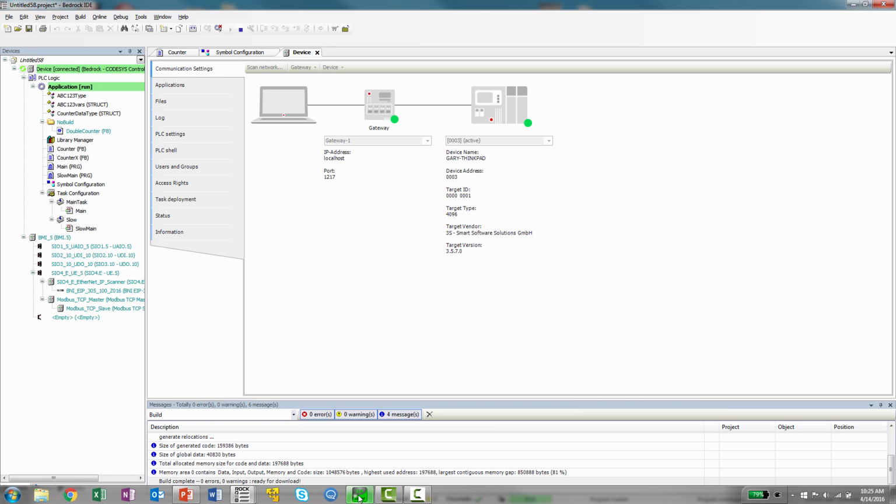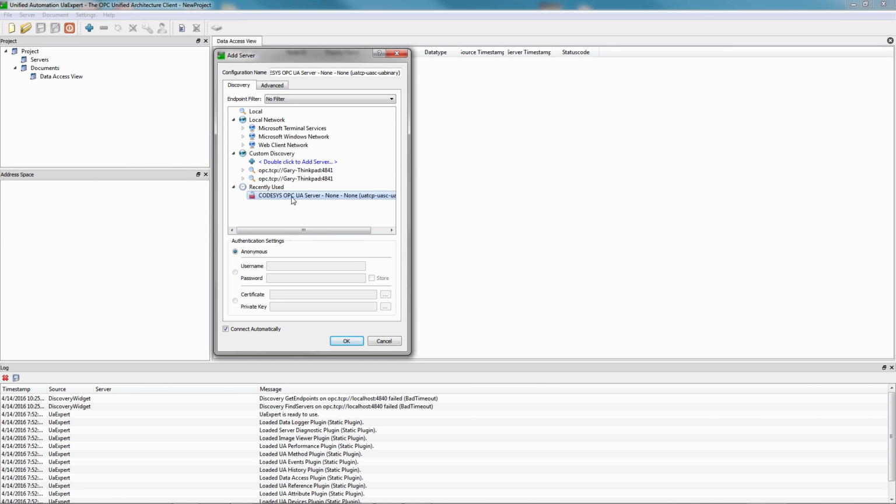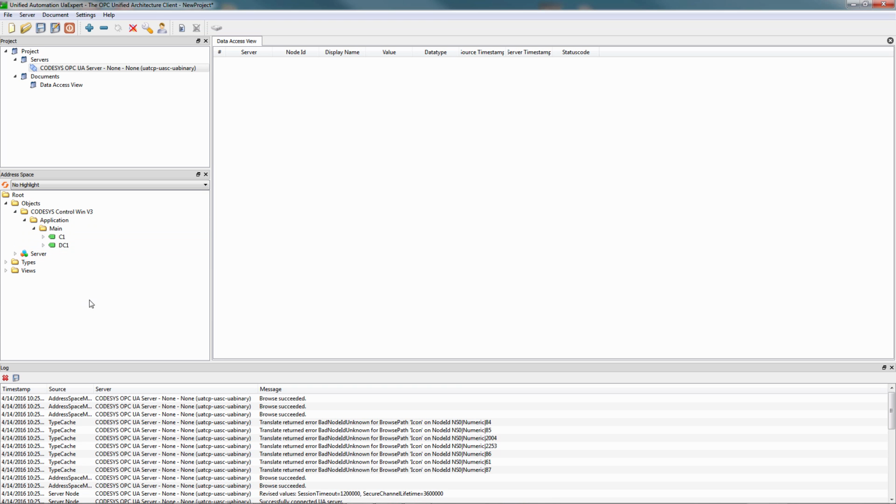And then what we can do is go to any OPC-UA browser that we want. We can go find our Bedrock, the full-featured controller that's running on our laptop, and then we can go and find our variables. Now notice two things here unique to OPC-UA that are infinitely better than the bad old days. First of all, I can browse. OPC-UA has this browse feature, so I can browse all the symbols that are exposed on the OPC-UA server.